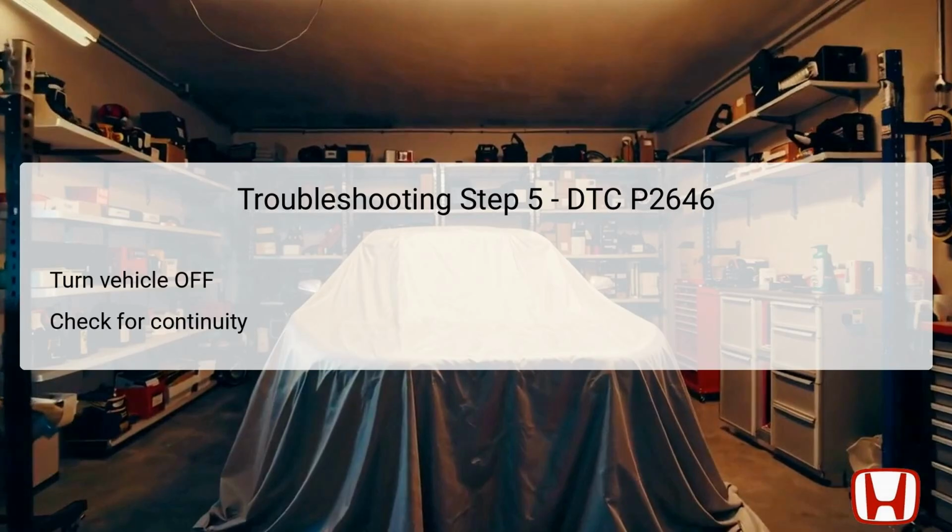During this final troubleshooting phase, the vehicle must be turned to the off-lock mode. The technician then jumps the SCS line using the Honda Diagnostic System, HDS, and waits for at least a minute. This step assists in disarming the airbag system for safety during the service process. Following this, the technician disconnects the PCM connector E80P to perform a continuity check.